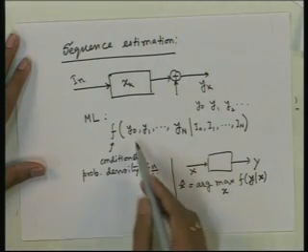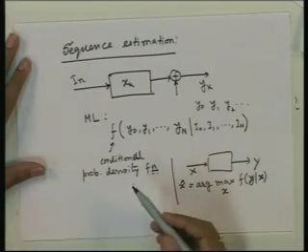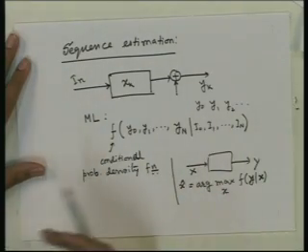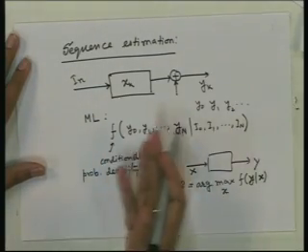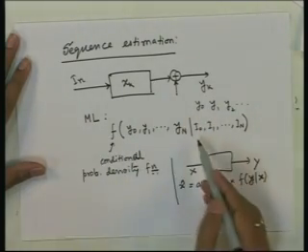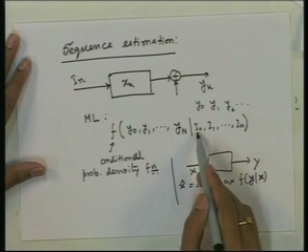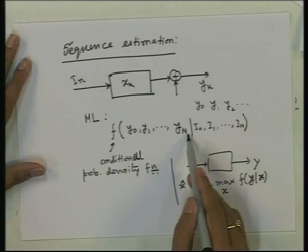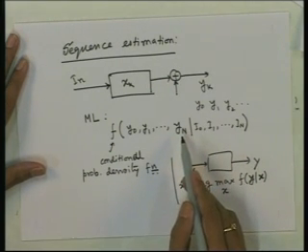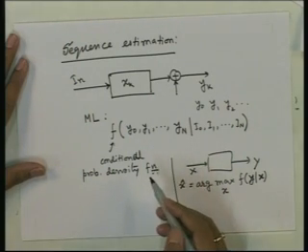And also, can we wait to receive all 1 million symbols before we decide even the first symbol? That is what this says we should do. We should receive all the n symbols and only then decide all these together, including I naught. So, to decide what was transmitted at the 0th symbol interval, we need to wait for all these n symbols to be received, and that is too much delay to be afforded in practice.